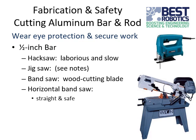With these, make sure you're wearing eye protection, and make sure you're securing your work. You don't want little bits of hot metal flying out and hitting you in the eye or anything. You should be able to cut that. Aluminum in general is a really soft metal, so it's relatively forgiving and relatively easy to cut for being metal.